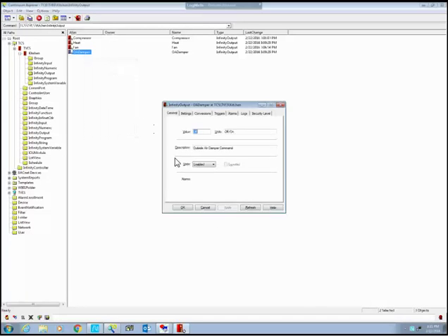This one, an 851, those are tri-state, meaning if it is typically for a damper or some type of modulation where you turn it on, it drives it one place, you turn it off, it stops it. If you want to drive it the opposite way, you set it to -1. But they call that a tri-state point. So it's got 1, off, and -1 states, hence the word tri-state.